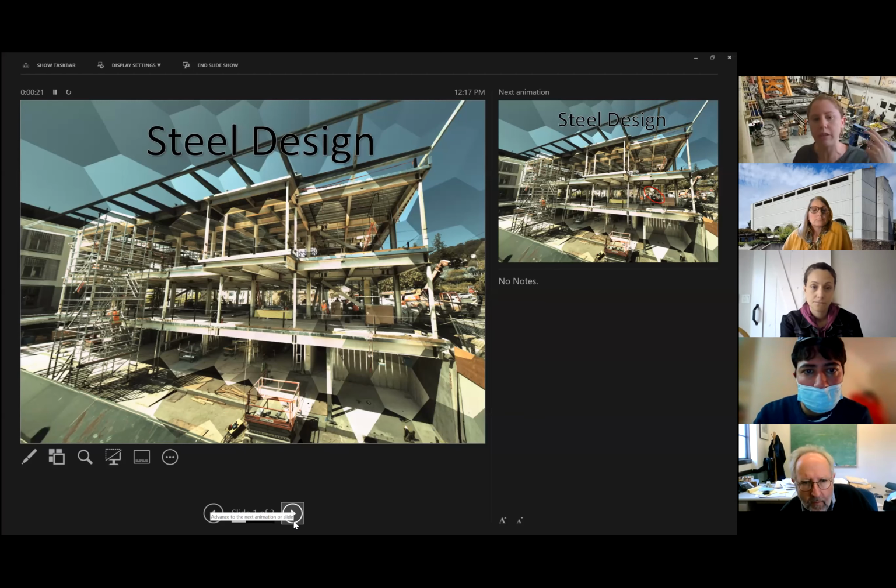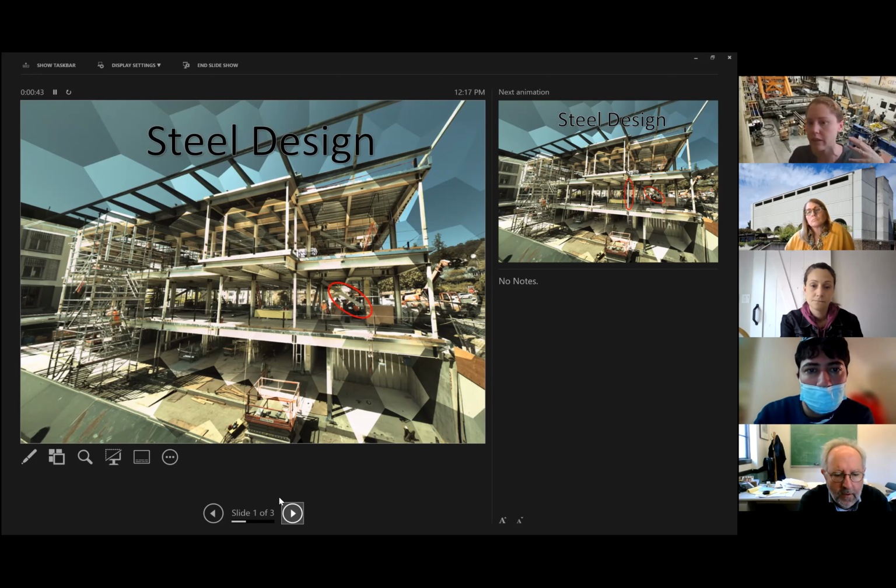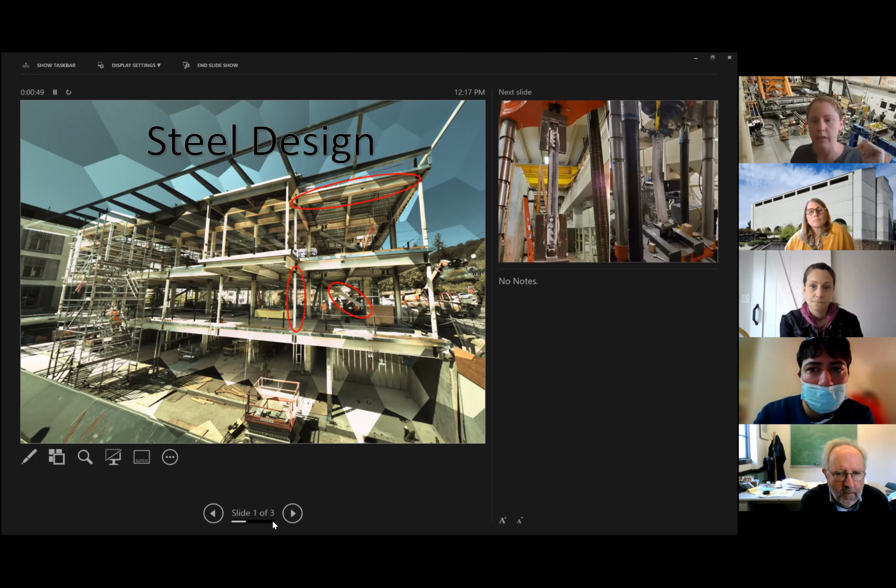And you can see that we talk a lot about how our loads come through our structures. So things going from the slabs to the beams to the columns, how things are transferred to the ground, lateral load systems like wind and earthquakes. And so we bring that together and talk about all the forces on these different members and how we would need to design them. So for example, how we would design a brace for tension and compression, how we would design a column for compression, how we would design a beam for the bending that's going to occur. So all of these have different forces on them internally and have different failure mechanisms. So we have to consider all of those things in our design.